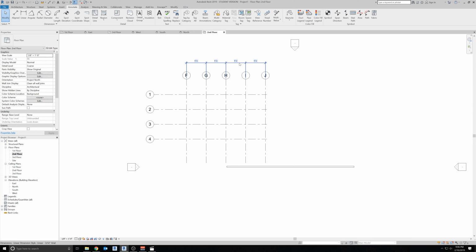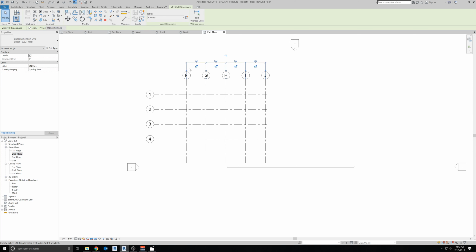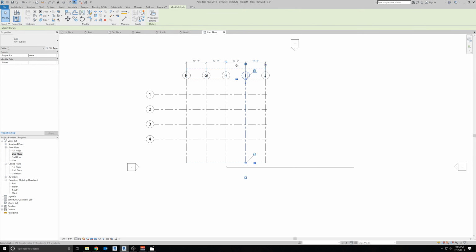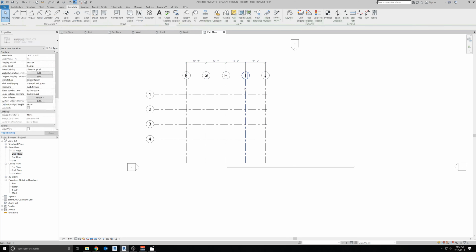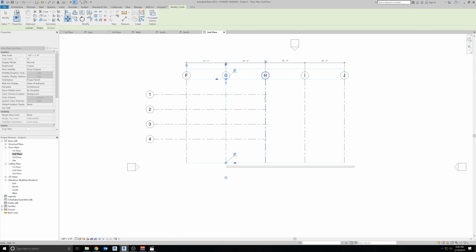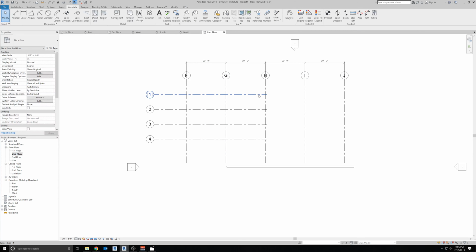And a good tip for you guys is that if you don't want to see the sign equal, when you click on equal, you can just select the dimension, and here select value. If then I want this to be 12 instead of 10, I can move it, and so on and so forth. So let's say we want them to be 15 apart, or let's do 20 apart. Perfect.